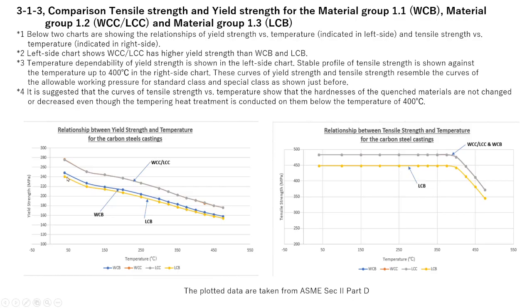At ambient temperature, internal stress and yield strength are balanced. So the internal stress has a 280 megapascal stress, but on heating up to 350, the yield strength decreases and the internal stress is also reduced to 200 megapascal.